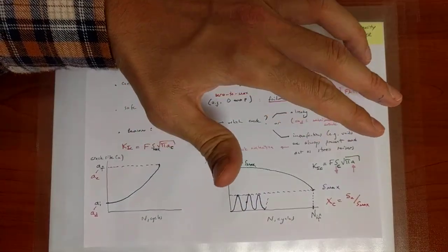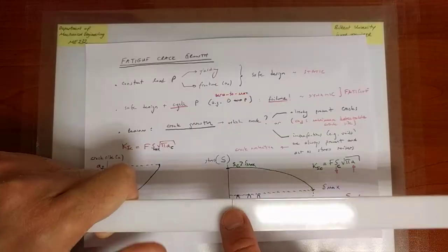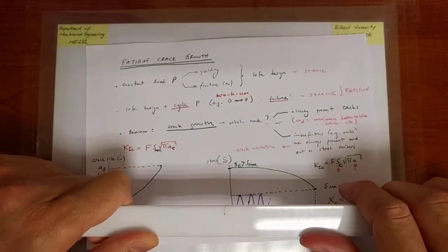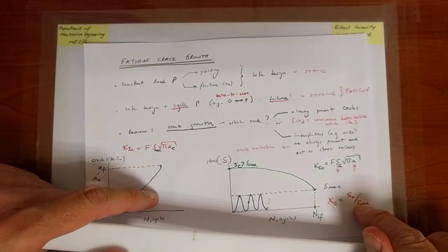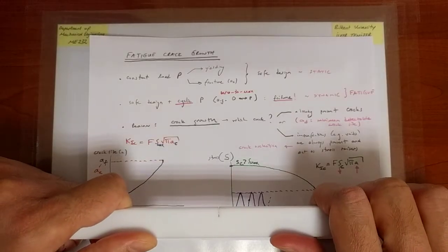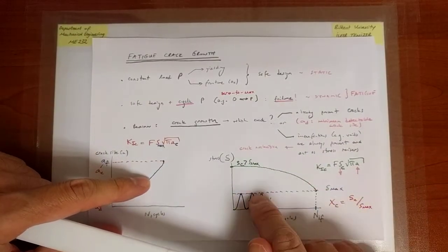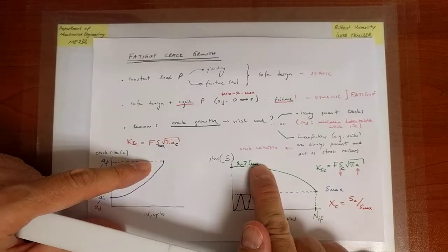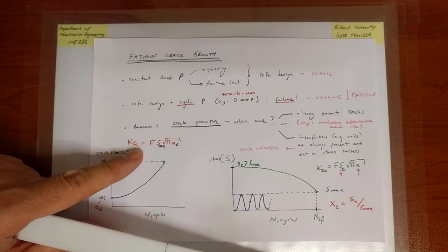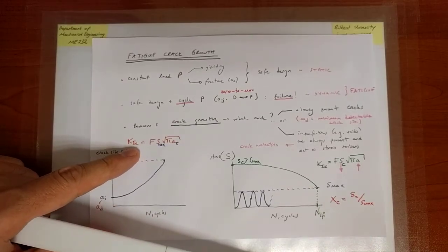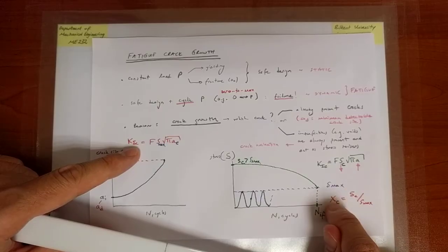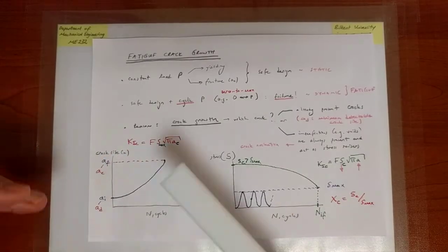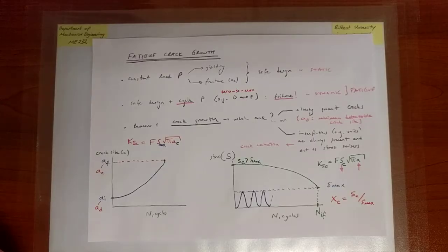So I have a plane wing, right? And the plane wing actually contains a crack, and you know that it's there, and the plane under flight conditions experiences the maximum load. You expect it to experience a maximum load of S max, but it goes into turbulence, and all of a sudden, although you expect it to experience S max, the load shoots up to a certain value, and you'd like to assess how much it can shoot up, how safe you are. So the largest it can shoot up to is SC. You expect that to happen. If this accidentally happens, then your safety factor against failure would be SC over S max. So that's the idea of introducing the green line.